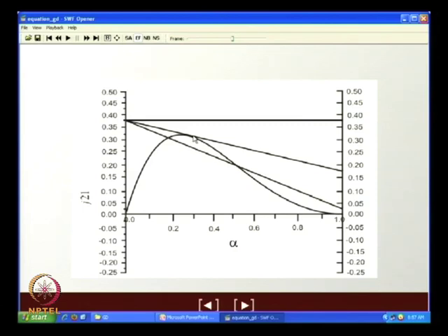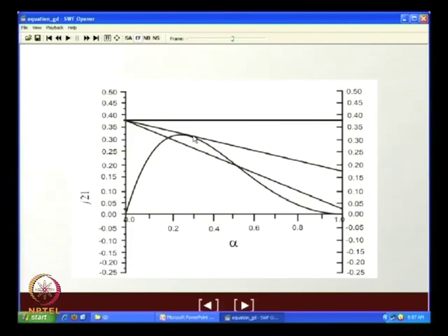What does it denote? It denotes the limit of countercurrent operation. When does the limit come? Under flooding conditions. Is it clear? So, this point of tangency gives you the flooding condition beyond which countercurrent operation is not possible.